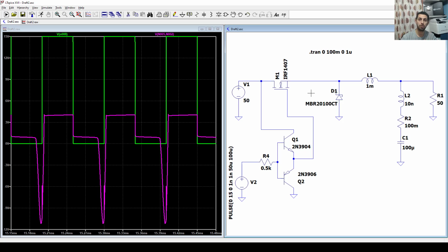This is the problem of high side switching. You have to use different topologies. That topology is very good for low side switching, but for high side MOSFET driving, it still lacks the ability to turn it on. So one solution for that is called the Bootstrap. The reason why this configuration can't drive that gate to be higher than the source by 10 or 20 volt is because it doesn't have the supply for it.